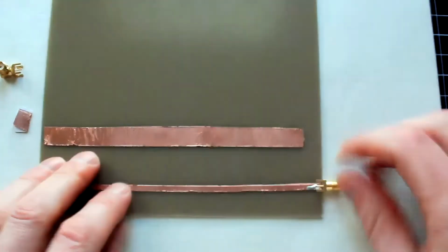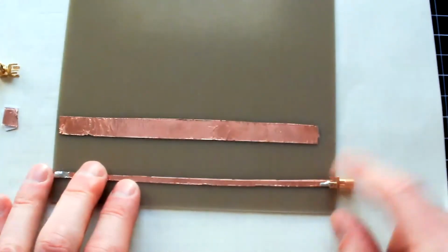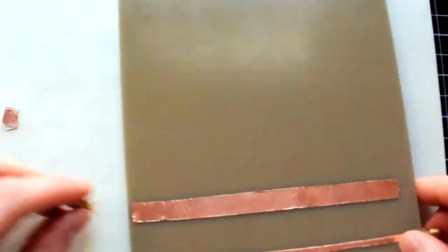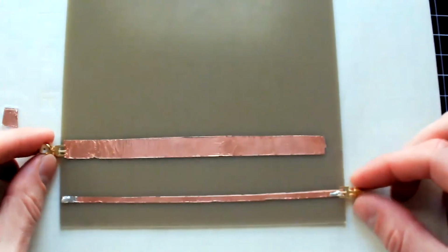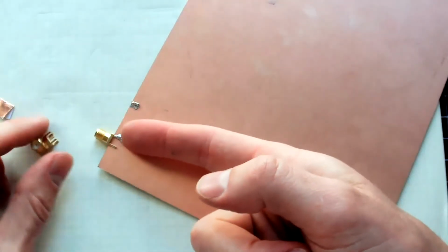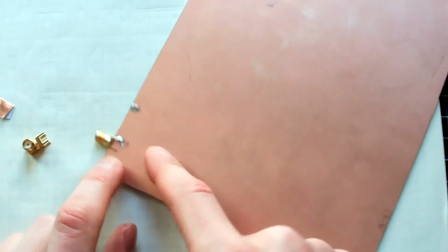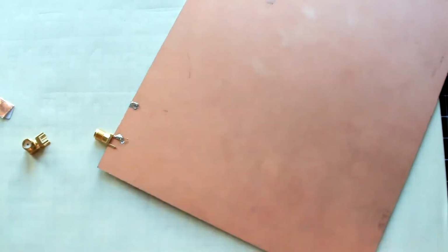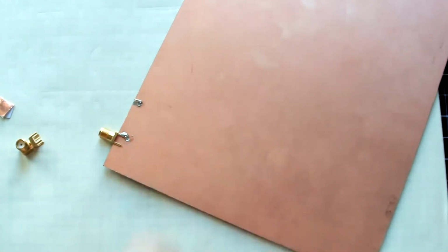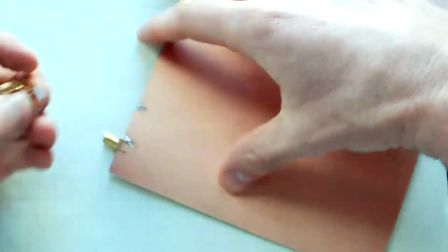But you can try and solder if you want. It won't be that hard to solder the top. It's the back side that you'll have the most trouble with here. So did you use the oven on the back? Did I use what? Did you pop it in the oven to heat up the back plane before soldering? No, I just cranked the iron up to full blast and held it there for 10 seconds, and then it barely managed to make a connection. But it's really difficult. It's not very reliable to do that. Like this one, I tried multiple times and couldn't get it to work. I got lucky on this connection. So like I said, that's why using something like a friction contact seems to be a better idea.